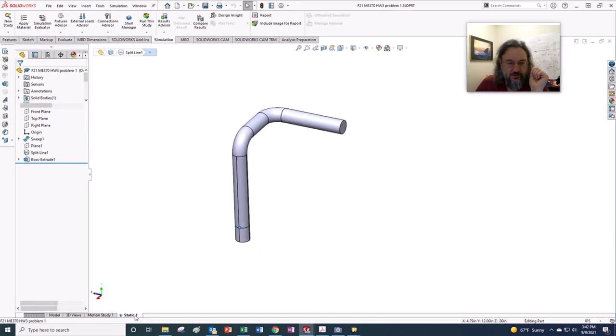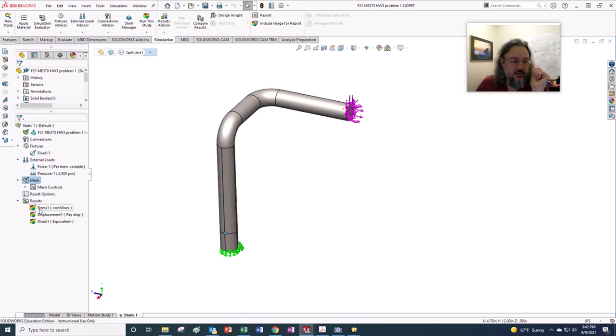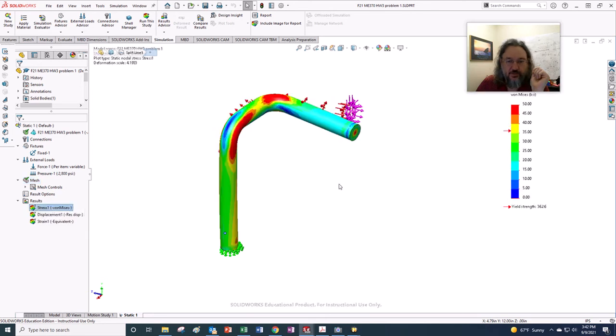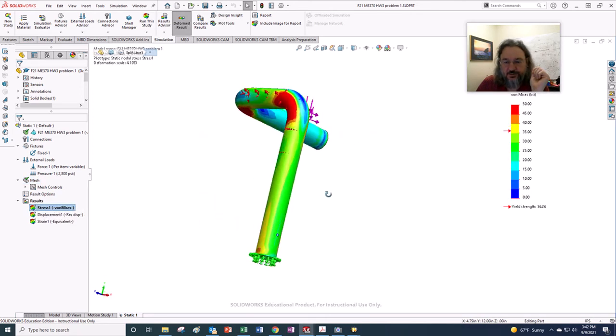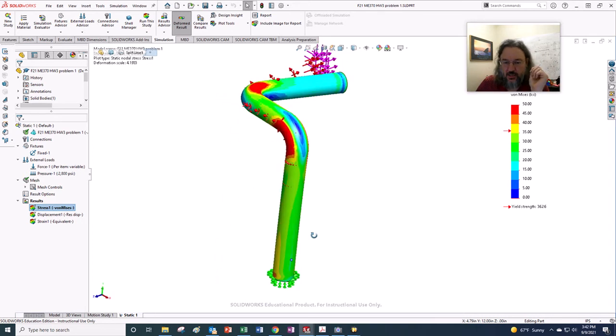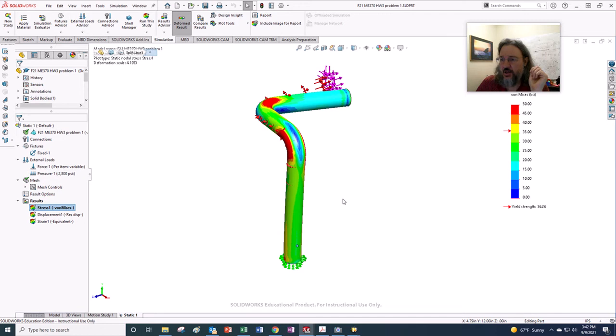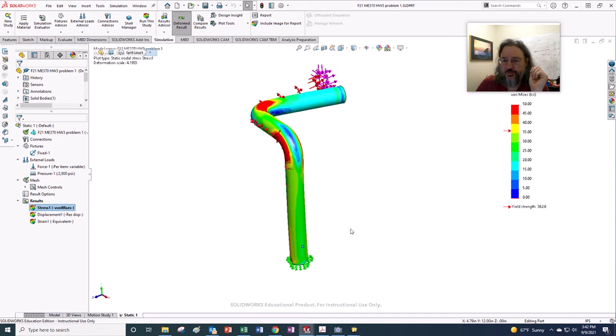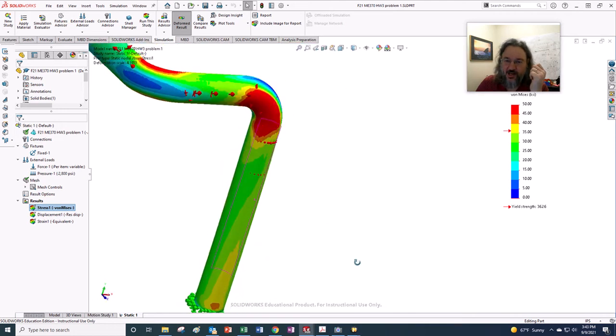All right, so I think the stresses I'm showing initially here, after performing this, are called von Mises stress, and we'll learn more about that in Chapter 5 of Shigley. But for the time being, just think of it as a really useful single, always positive value to assess the thing. It's very useful for comparing to the material strengths that you get from an axial pull test.